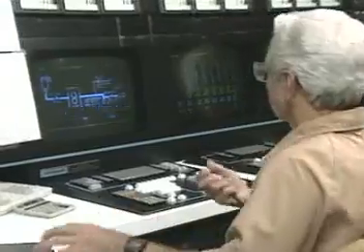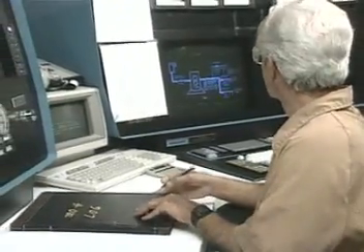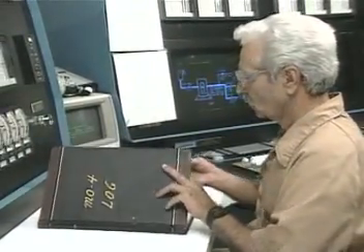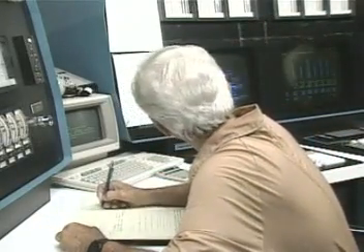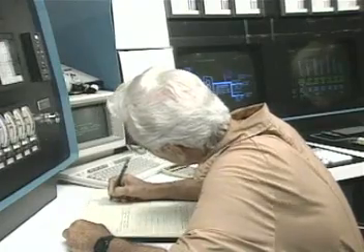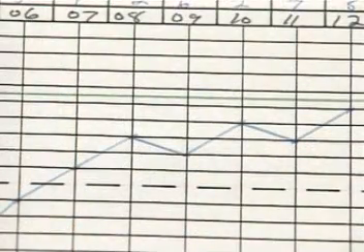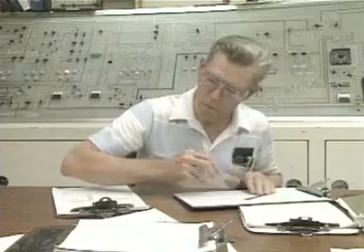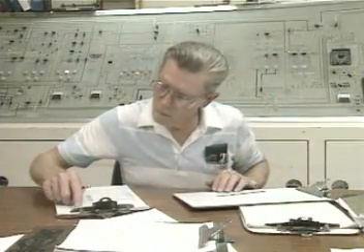While control charts provide good information about whether a process is in control or out of control, no control chart can identify the problem that's causing the process to be out of control. To do that, additional information is needed. One way to help identify problems in a process is by keeping a written log of what's going on in the process. Keeping a written record of process conditions can sometimes make it easier to narrow down the cause of a problem. Then, if the control charts indicate that there's a problem in the process, the operator can refer back to the log for more specific information.